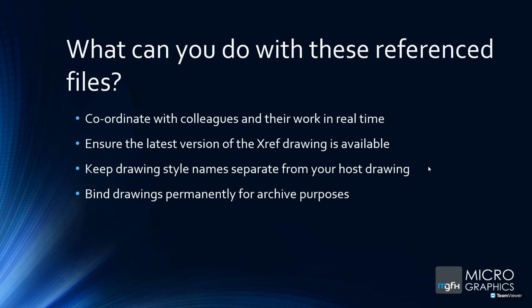So let's go collect all the projects, make a copy of it inside this drawing over here, and then you can go archive that so that when you, for instance, need it later down the line, a couple of months later, you're not going to have the problem, if it's still Xref, that you open it up and it's, oh, this Xref file is missing, that Xref file is missing, and now you've got to go find it, and it's a bit of an oopsie. So by archiving it, it brings everything together, binds it, puts it in one file so that you've got it for archive purposes.